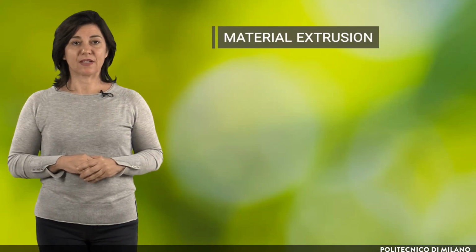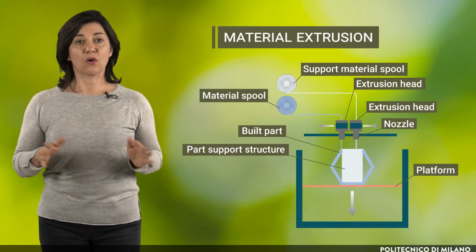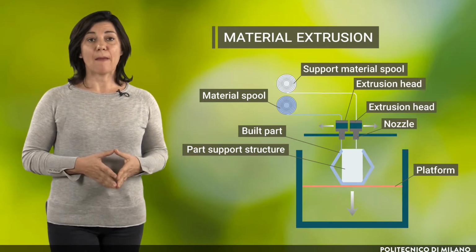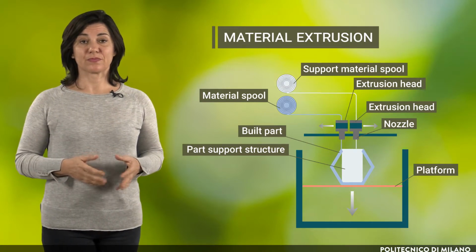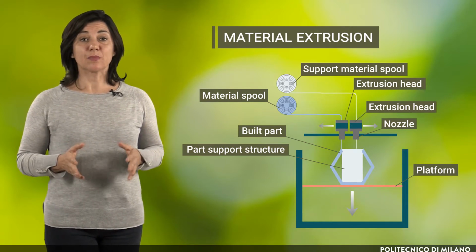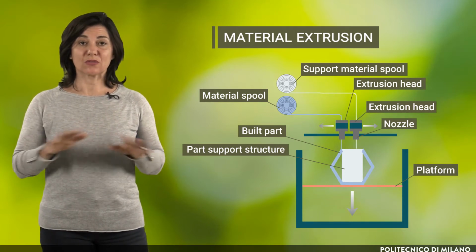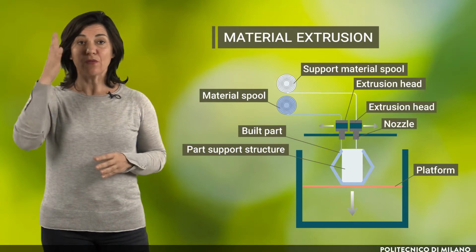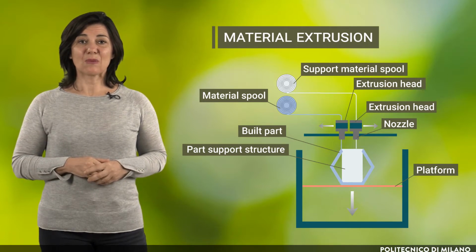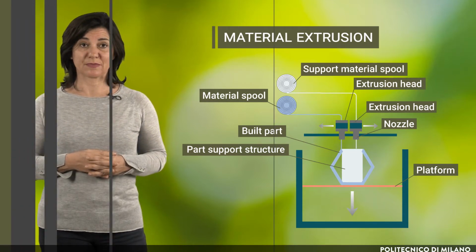Material extrusion is defined as an AM process in which material is selectively dispensed through a nozzle or orifice. The feedstock is typically a thermoplastic filament, and binding occurs through thermal reaction. Material is drawn through a nozzle, where it is heated and then deposited layer by layer. The nozzle can move horizontally and the platform moves up and down vertically after each new layer is deposited. It is a commonly used technique on many inexpensive domestic and hobby 3D printers.